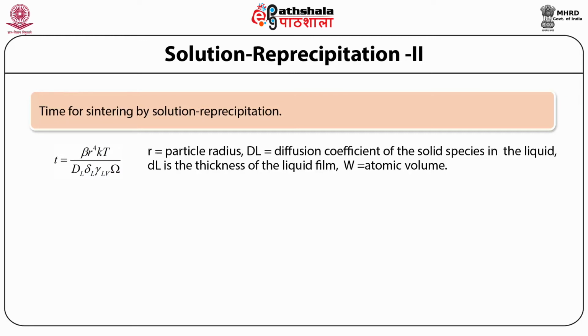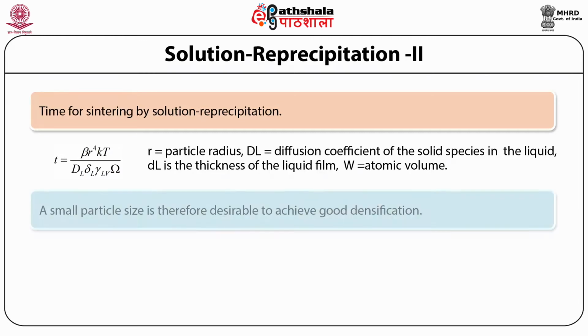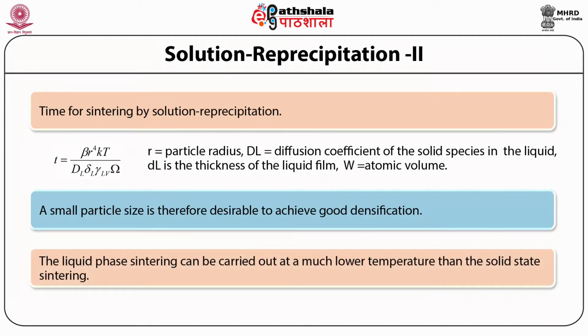Note that the time increases as the fourth power of the particle size, and a small particle size is therefore desirable to achieve good densification. As the diffusion coefficient depends exponentially on temperature, liquid phase sintering is much more sensitive to temperature than solid state sintering. Liquid phase sintering can be carried out at a much lower temperature than solid state sintering.